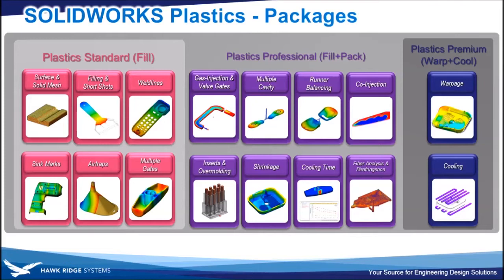by maybe just a part designer that doesn't really have any knowledge or input on the mold setup. Plastics Professional, which is the middle package there, would be the minimum level of the software required to do any of these kinds of simulation with insert overmolding, being able to specify that there's an existing insert of a different material in the mold.